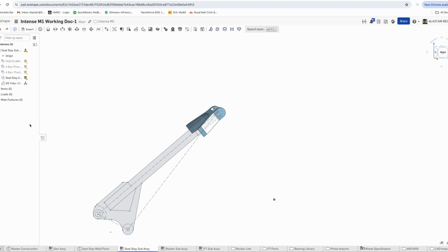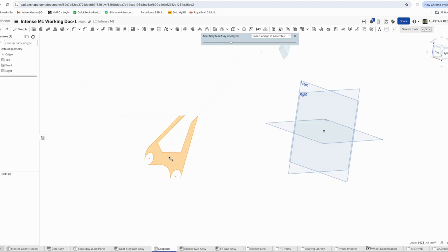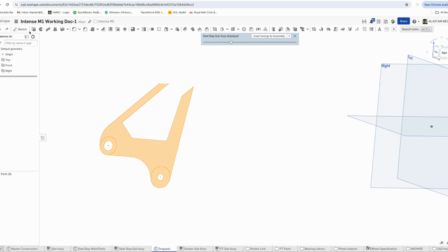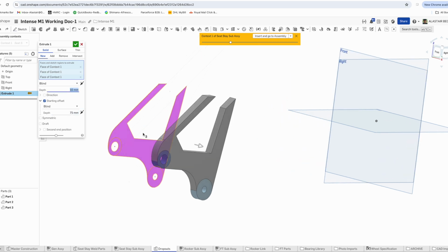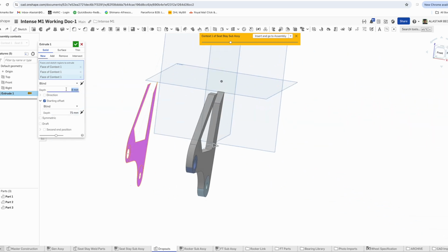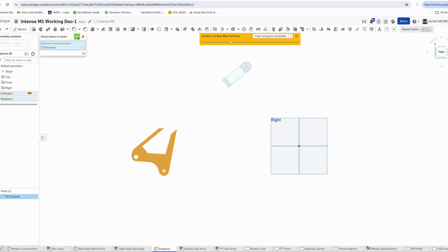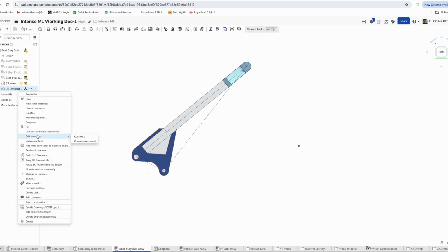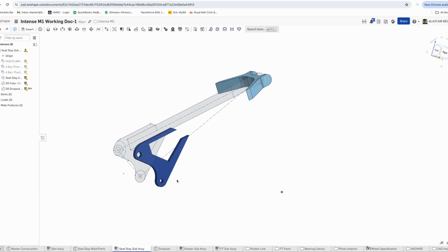Again, so we've stuck that seat stay clevis into the seat stay subassembly, and now we're going to start working on the dropouts, which I originally thought were just a plate, like a 5mm, 6mm thick plate, but it turns out they must have been a forged part, so they had a bit of contour to them and some pocketing on the inside, which I later figured out. So you can ignore this bit at the start. I ended up going back and beefing it up because it's got to have a bearing pressed in at that lower horst link position, so that needed a little bit more wall thickness, and where it joined at the seat stays, it didn't need to be quite as thick.